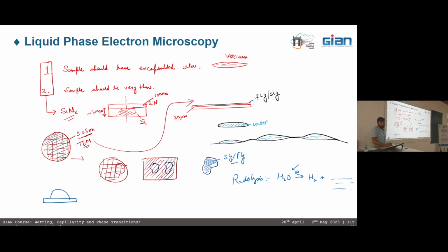But this is mostly a skill-based technique. There are certain do's and don'ts which you have to take care of when you perform this experiment. The first very critical step is that this copper is just 30 micrometers, which means it's very flexible and we can damage it very easily. You must make sure that this is ultra flat, because we are talking about a film which is just 1 or 2 atoms thick. Its thickness is just 0.3 nanometers.